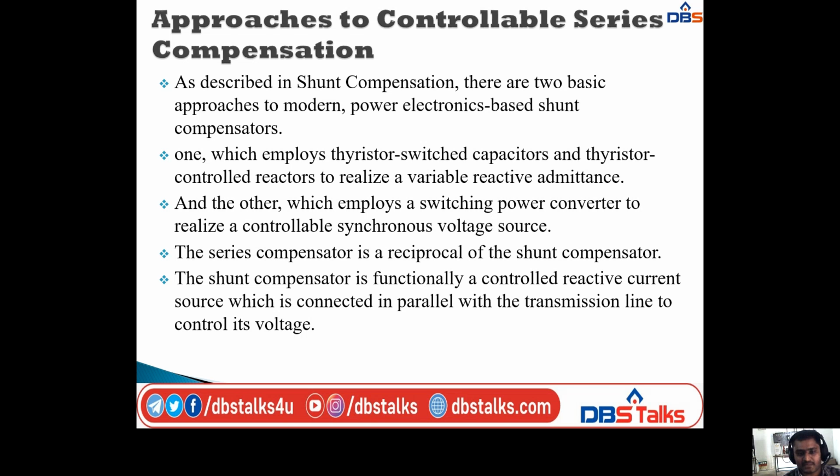The series compensator is a reciprocal of the shunt compensator. That means the shunt compensator is functionally a controlled reactive current source, which is connected in parallel with the transmission line to control its voltage. That is the shunt compensator.